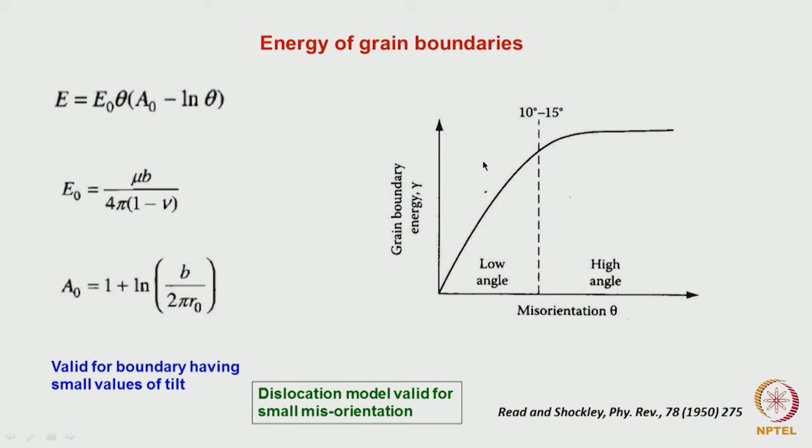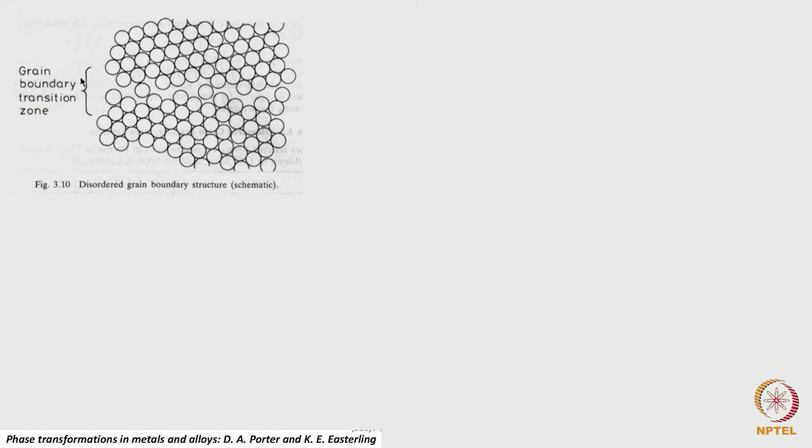What is the grain boundary energy which has been seen beyond this value? It is being shown as nearly a straight line, okay. But let us see whether it is so or whether it can have some variations, okay. That will become clear. Here what we are showing is atomic planes. You look at it, close packed plane, how they are arranged. You look at this direction here, and in this one, the close packed direction is in this way. Okay, these two, if you look at it, the misorientation between them is very large, correct?